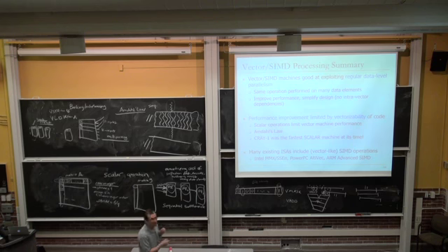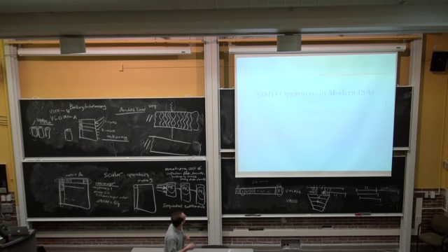So many existing sequential ISAs also include SIMD operations, if you will. So this is not limited to a machine that's all vector processor to which you add scalar processing. Many existing scalar ISAs include vector-like operations. And you may have heard of some of these. ARM has Advanced SIMD, for example. Intel has MMX, right now SSE. And probably they're coming up with some other acronym that has two of the same letters first and something else next. So let's take a look at these very quickly.